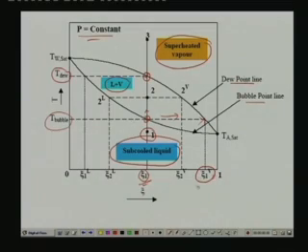So, as you continuously heat it, you will find that progressively the vapor that is forming will be rich in water, will be stronger in water also. So, initial vapor to be formed will always be rich in the low boiling point substance. In this particular case, it happens to be the ammonia. So, that is what I am showing here. The first vapor bubble is quite rich in ammonia vapor. So, the concentration is given by zeta 1 V, V stands for vapor as I explained.